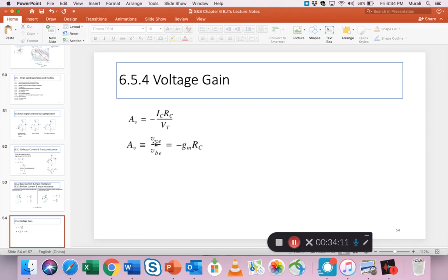Can I just look at a transistor circuit and say, yep, I can guess what the amplifier gain will be? Yes, if you can calculate GM, which is not too difficult because all it needs is the collector current, because V thermal we generally know, so GM is not difficult to calculate.